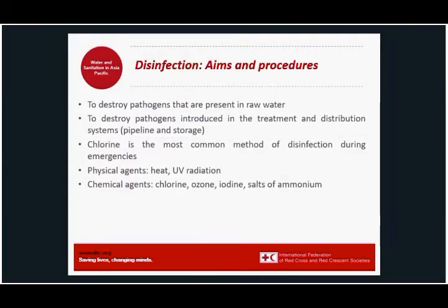Disinfection. The other main important treatment process we use after having removed the particles is disinfection. We can use disinfection to kill pathogens or disease-causing microorganisms in the water. We can't see these microorganisms. Bacteria is 0.3 microns, for example, whereas viruses can be 0.005 microns. As a comparison, a human hair is in the order of 100 microns in diameter. So bacteria and viruses are several orders of magnitude smaller than a human hair, and it's not possible to see these microorganisms.